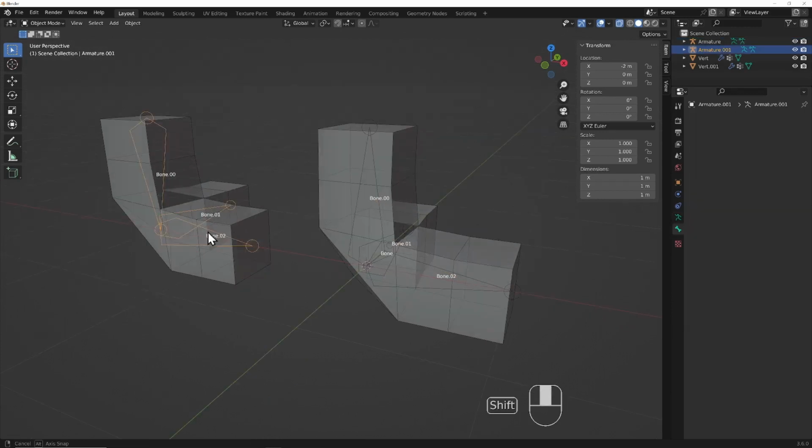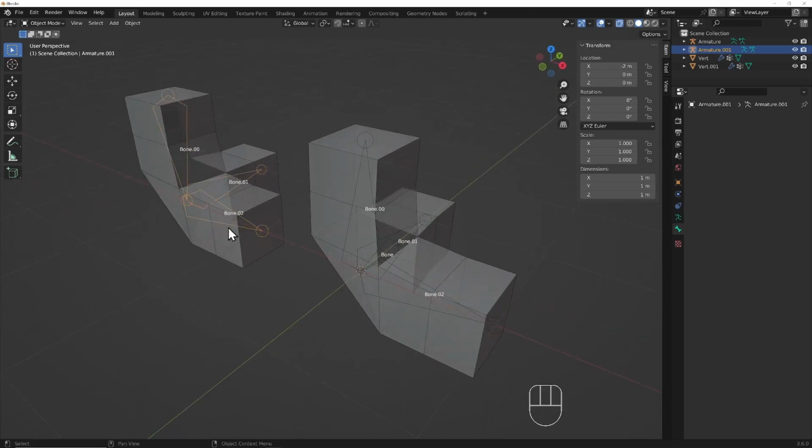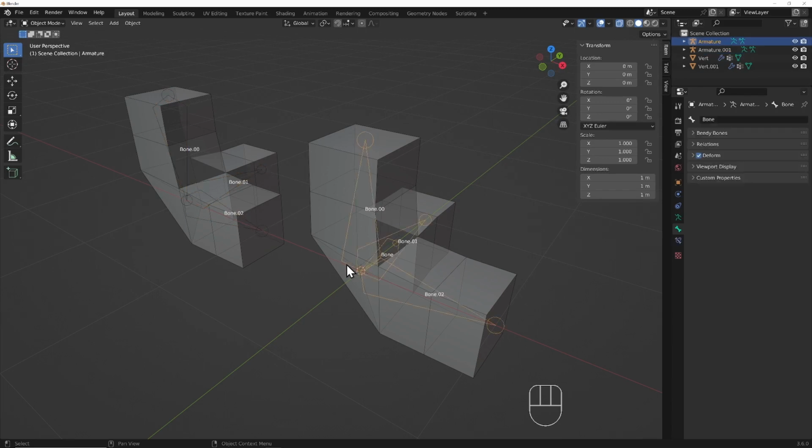The armature on the left only has 3 bones. It begins where we marked the vertex's root and extends down, then branches out along the X and the Y arms. However, the armature on the right is a little different. It consists of 4 bones. An extra root bone has been generated from which the 3 arms branch out. Any vertex marked root which connects 2 or more edges will have a root bone created in this way.